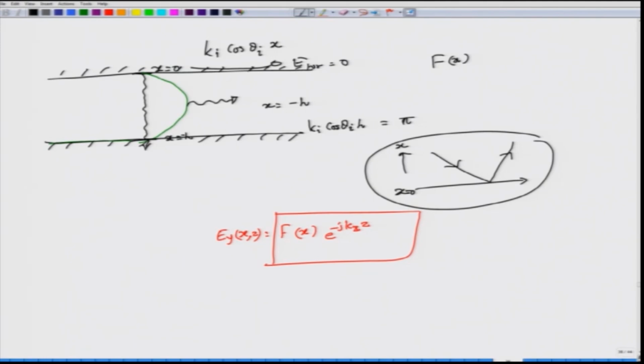So, what you actually have in this kind of a scenario where I have two perfect electric conductors, okay, with this kind of a boundary, is that the pattern between the two perfect electric conducting walls is a function of the x direction, which is this vertical direction that I am showing, and this pattern actually moves along the z axis, and it is not just one particular pattern. So, it is not only one half sinusoidal cycle, it could be one complete sinusoidal cycle, it could be 3 half sinusoidal cycles, 4 half sinusoidal cycles, so on and so forth, and all these patterns are equally valid solutions for this problem that we have considered, okay.